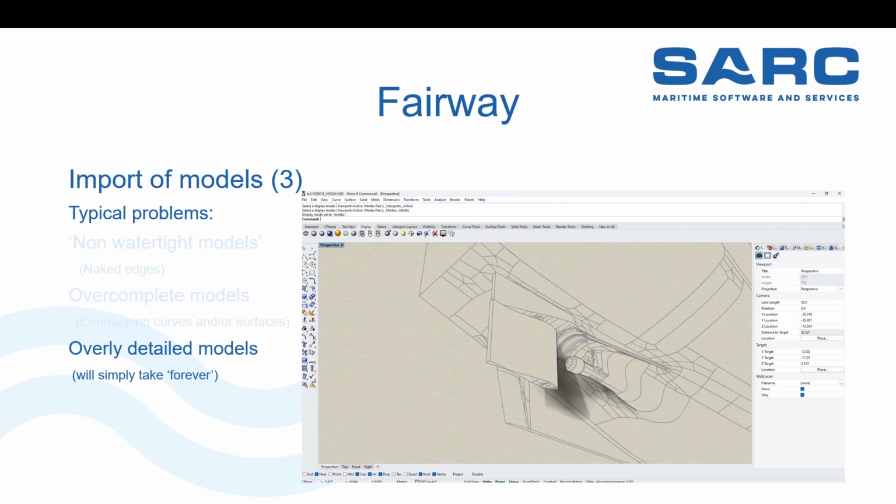And much of the time I don't convert it to a solid, but I keep it as only lines. Then make a new solid, and create your solid as close to those lines. It's a workaround, but that's very helpful when you have a goal. So you can put this in the background as a separate object and create a new model to match these curves. You don't need all of them, you only need a few sections, a few waterlines, a few buttocks. If you copy those, then you're already halfway there in reconstructing this model.